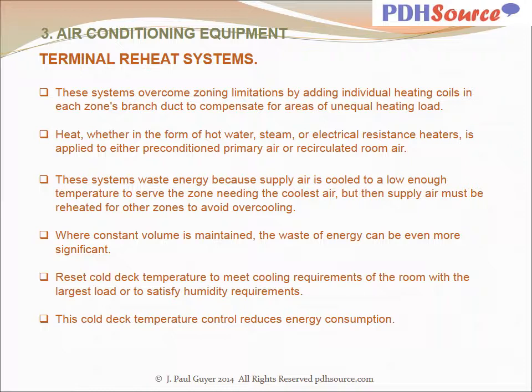These systems waste energy because supply air is cooled to a low enough temperature to serve the zone needing the coolest air, but then supply air must be reheated for other zones to avoid overcooling. Where constant volume is maintained, the waste of energy can be even more significant. Reset cold deck temperature to meet cooling requirements of the room with the largest load or to satisfy humidity requirements. This cold deck temperature control reduces energy consumption.